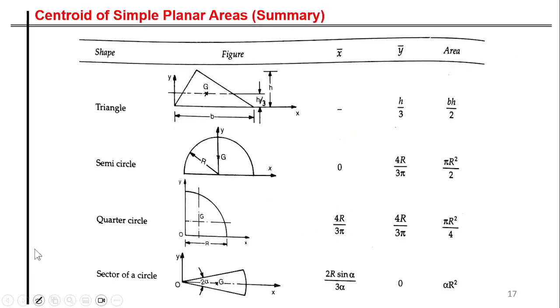So these are all the things that you are supposed to make note of. Please do understand where your reference axes are. Based on the location of your reference axis, these x and y bar locations are going to change. Now, there is a small point that I wanted to highlight here. If you are trying to draw a set of reference axes that are going to be considered